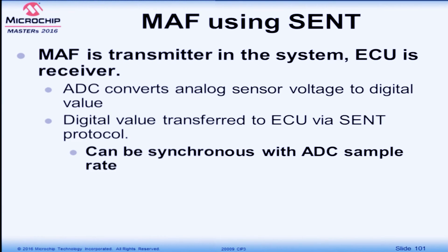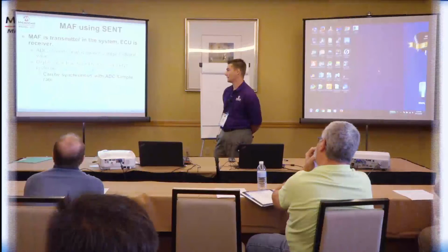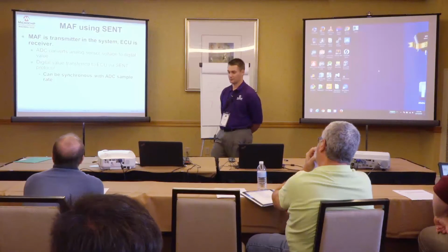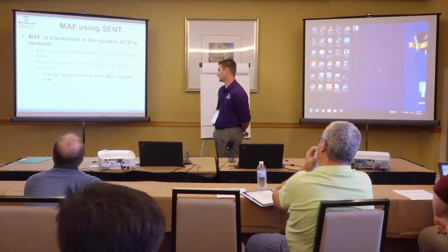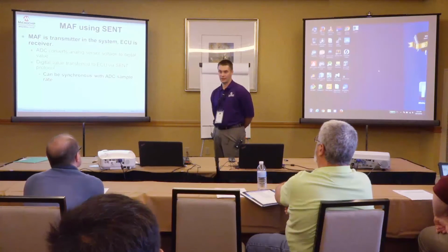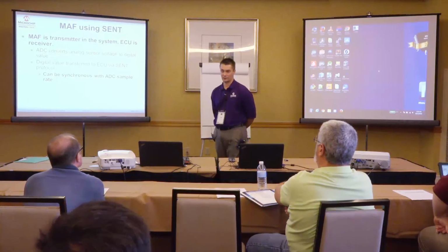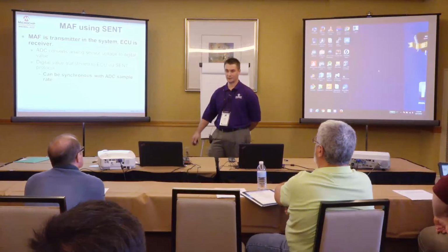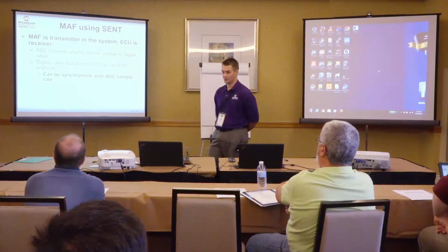So in this case, our mass air meter is our transmitter, and the receiver would be the engine control unit. And again, the ADC in the device is going to convert that analog voltage typically into some digital value and send it off on the SENT bus. Could do that synchronously with an ADC sample, or you could also have it just transmit back to back with the same value, and then when an update comes in, the data will change on the bus either way.